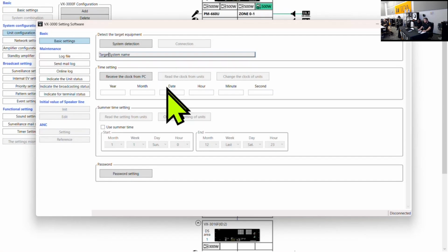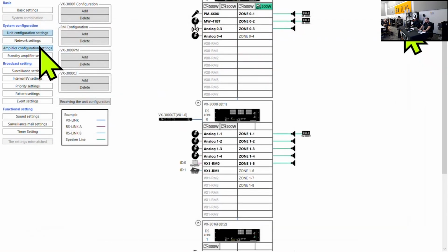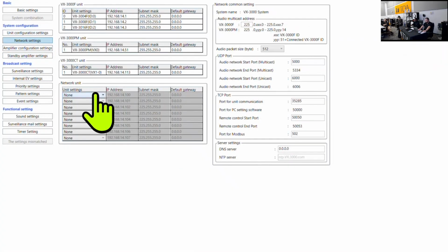If you're talking about VX3000 and SX2000, they are not compatible at the packet audio level. They cannot transmit audio via network from SX2000 to VX3000. The only other TOA device that can actually send audio to the VX3000 would be the NX300.